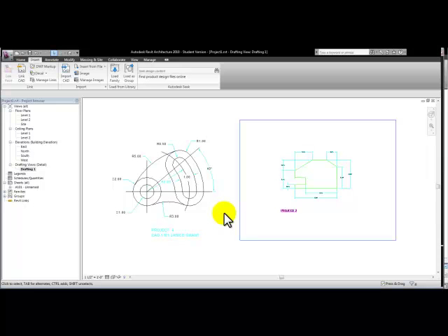Revit can import and link several CAD file types. The import CAD function is similar to inserting blocks in AutoCAD. You can insert or import a CAD detail and then explode it so that it becomes a permanent part of the current drawing that you're in. Or you can link a file, similar to XREFs in AutoCAD, where there's an actual link. If the original drawing changes and is saved, you can reload that file in Revit.